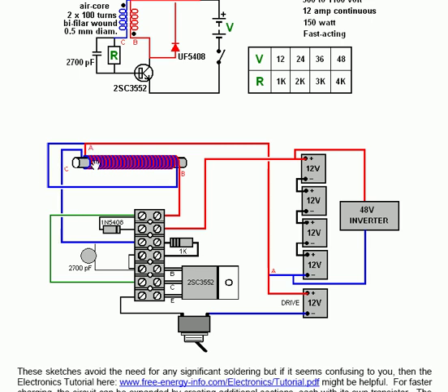If you're using plastic screw connectors from your local hardware shop to connect this circuit together, they come in several different sizes. If you don't get the smallest one, you may find that the transistor pins, which don't bend easily, are not the right spacing for these connectors.